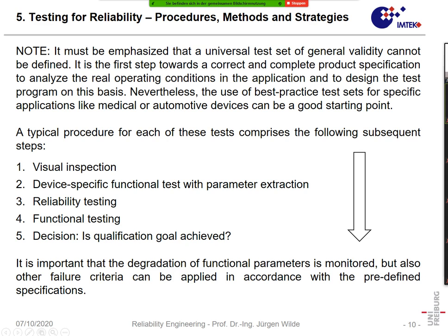And what is necessary is that the initial parameters due to specification are still met. So it doesn't help you if a sensor, which is crucial for life, is changing its sensitivity, its offset, and so on during the lifetime of your car. In that way, the complete system malfunctions suddenly. It is not really failed, but for instance, a control mechanism doesn't work properly anymore.